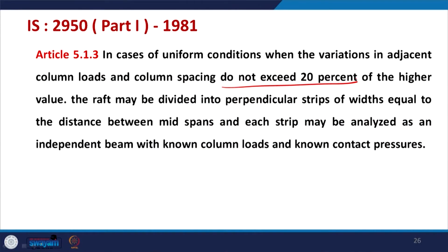So, first we need to check whether this variation is less than 20%. If so, we divide into perpendicular strips in both directions, between mid spans.